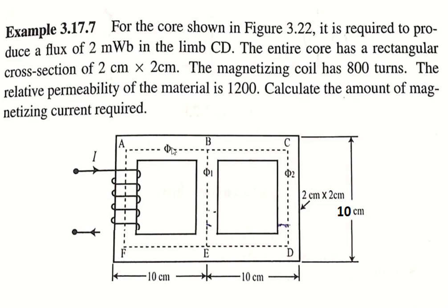We know that these parameters we have to assume. Phi total flux, phi 1, phi 2 be the flux in the other two limbs, and this is the total ampere turns we have applied, that is N into I. We have to apply phi to the portion where we are applying the current, or where the coil is. In that portion you have to apply the flux phi. Next we can see what the given parameters are.